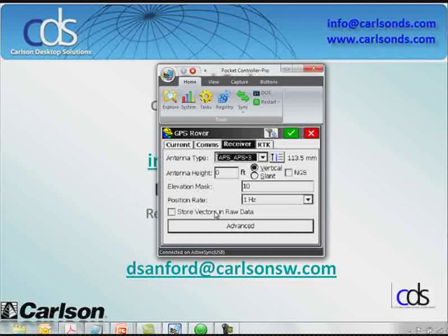This is a new option. To me, it's kind of like having your angles and distances in your raw file from your total station. Instead of simply saying, woohoo, here's my latitude, longitude, great, I actually have something I can post-process against, and I can actually use those measurements to recreate all of the survey data from the base position. So the raw vector is a nice thing that they added in. I know a lot of people have asked for it for a long time, and it was really nice to see it in the 2.0 releases of SurvCE.